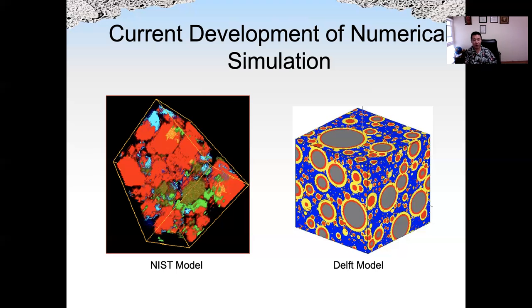They also have field tests, such as slump and air content, and then they take samples and bring them back to the lab for 7-day and 28-day strength tests. So they pretty much ensure everything in the lab before they actually cast the concrete, and in the field they also do quality control tests like slump and air content.